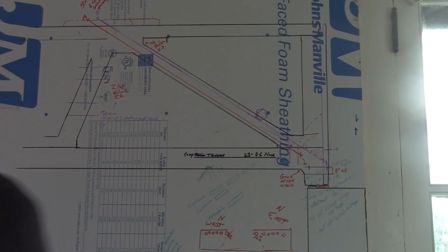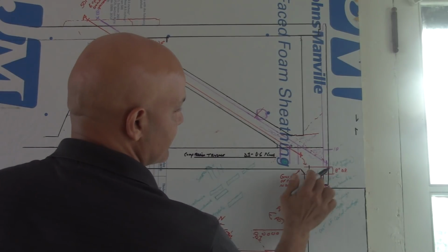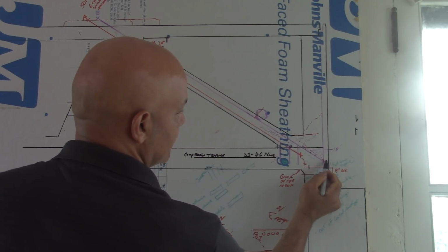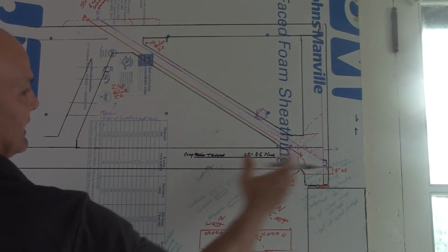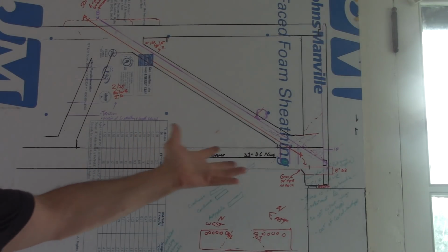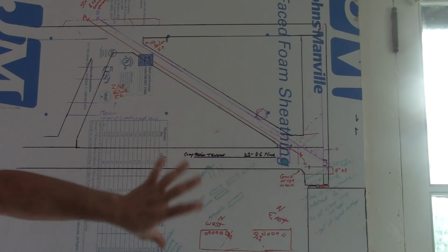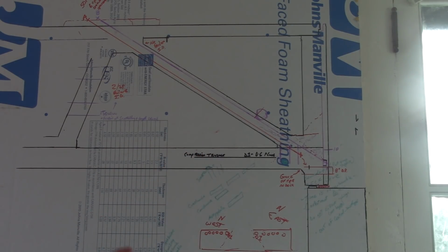I'm going to take a little liberty here. That's the outside, and here's the ductwork, and here is the post-tension bar, the tensioning through here. This creates that compression that stops deflection in a deck. Now, I think that it was theoretical, as we know, because it's never been done. The amount of compression, the amount of strands, and the compressive forces to keep this from deflecting. As Linda Figg said, it was all going to be under compression.